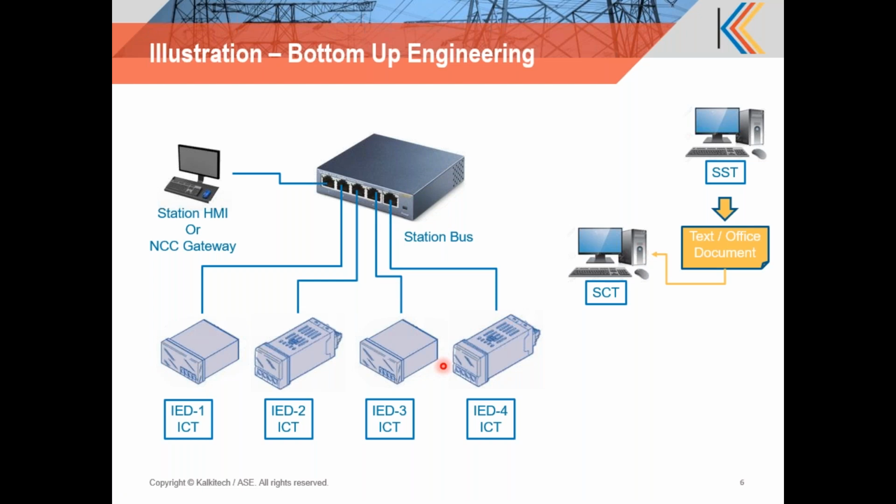All right. So the next step in the bottom-up approach is to go and perform some of the pre-configuration that we talked about, except that in the bottom-up approach, the pre-configuration is actually the entire configuration of the system. So the user knows what the requirement is, and he will perform all the configuration of the IEDs using the ICT. Knowing the requirements, the user can create the data sets, create the reports, create the GOOSE control blocks, assign names, IP addresses, and perform all the configuration of these IEDs using the ICTs.